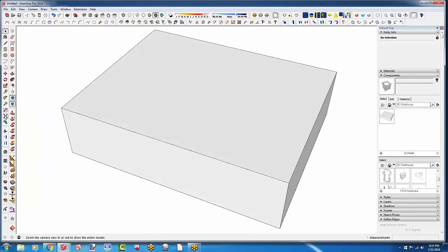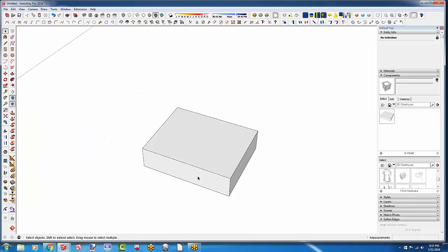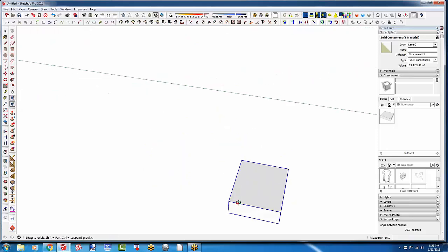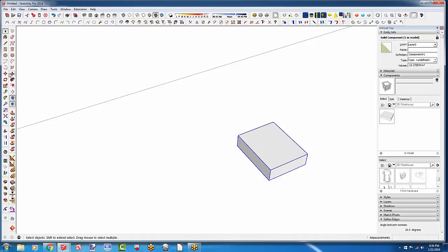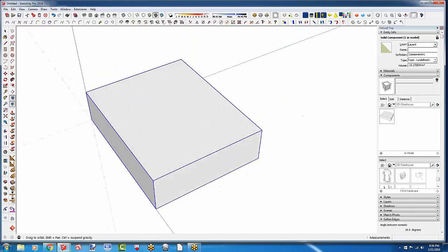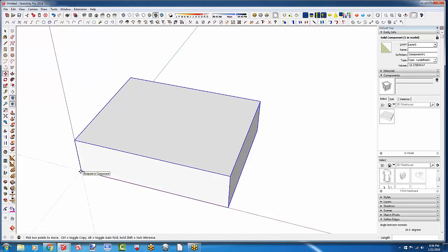And then when I hit zoom extents, I was able to zoom in on the chessboard itself and move it back to the origin, which you can do by typing 0, 0, 0 in square brackets. That moved the point that I'd started with, and I got it back to the origin.